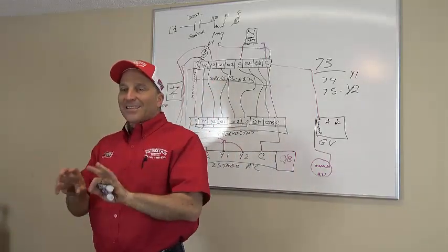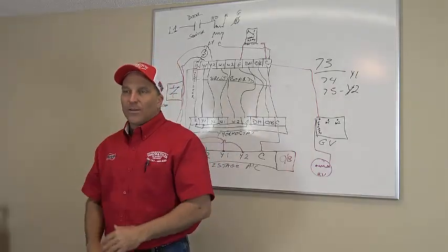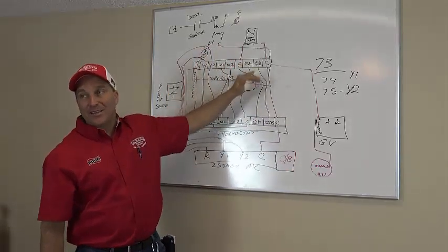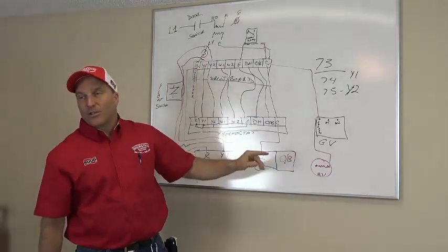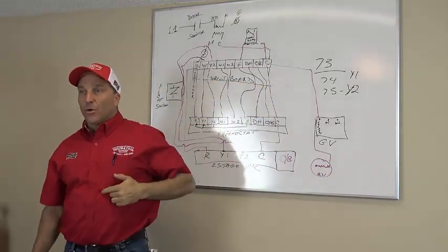It is a relay inside the circuit board, so they've got normally open, normally closed, and all that kind of stuff. So when this one gets energized for Y, the G de-energizes and energizes another relay which turns on high fan. That's the way the old two-stage would work.